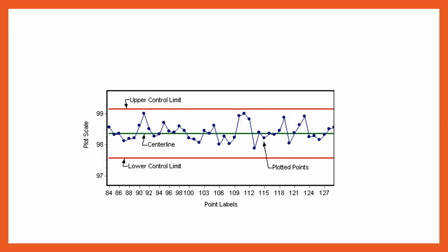So this chart gives the indication of where we have to take the real call, or stop the machines, or repair certain things, or modify certain processes. We have to do all these things so that the product we are making does not reach the upper control limit or the lower control limit. It should always be within these two. That is the significance of the control chart.